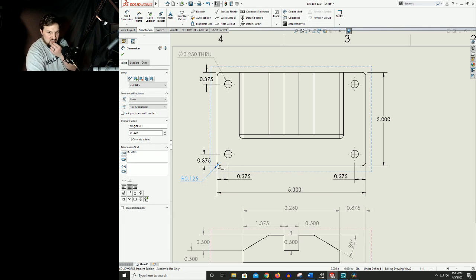Okay, we've got a square. That's what it's pointing at. In the circle, that's the end that the arrow is actually on. So I'm going to click on the square. And as soon as I click and hold and drag, you can see that that turns to a red kind of no access, don't drop it here point. However, if I come across any one of the other fillets, you can see that it changes to an arrow with a line. And that means that I can aim it at that, and I can drop it, and there it pulled that radius dimension up here.